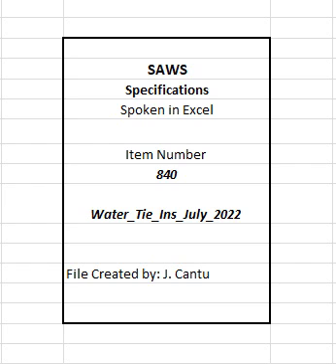6. A cut-in valve may be required to facilitate the shutdown. If approved by SAWS and there is no existing line item, a separate cut-in valve bid item will be established and negotiated for payment. 7. Tapping of CSC pipe is only allowed by the CSC manufacturer of pipe brand being tapped or CSC manufacturer approved by SAWS. See specification item number 820 concrete steel cylinder pipe installation.